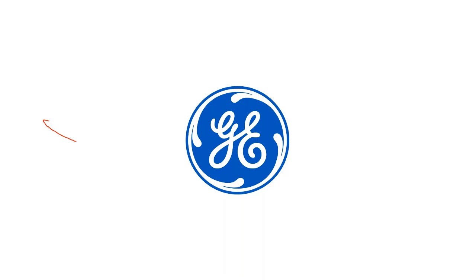RTD voting says you have to have this RTD at a high value and this RTD at a high value before you would trip. Part of the reason is that RTDs can fail, a lot of times in a high temperature condition. In other words, they're saying there's a high temperature.